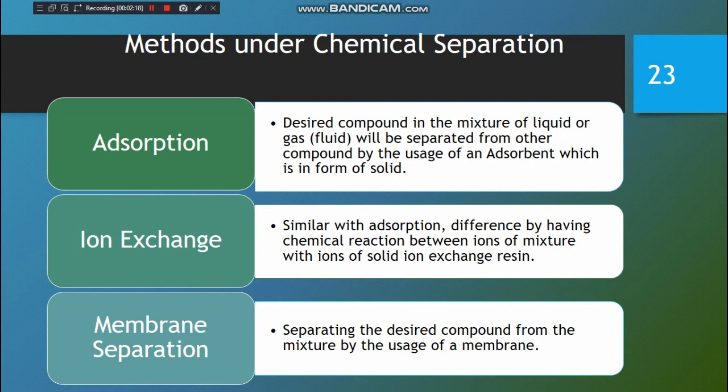There are different descriptions of ion exchange, which can be given as the following statements, based on the materials reference. First, ion exchange is also similar to adsorption in that solid particles are used in the separation process and regeneration is necessary. However, a chemical reaction is involved. And the other definition of ion exchange is the process which is basically a chemical reaction between ions in solution and ions in an insoluble solid phase.